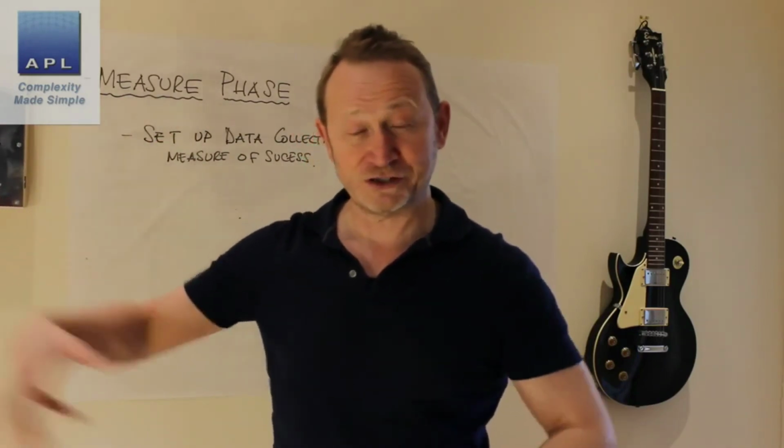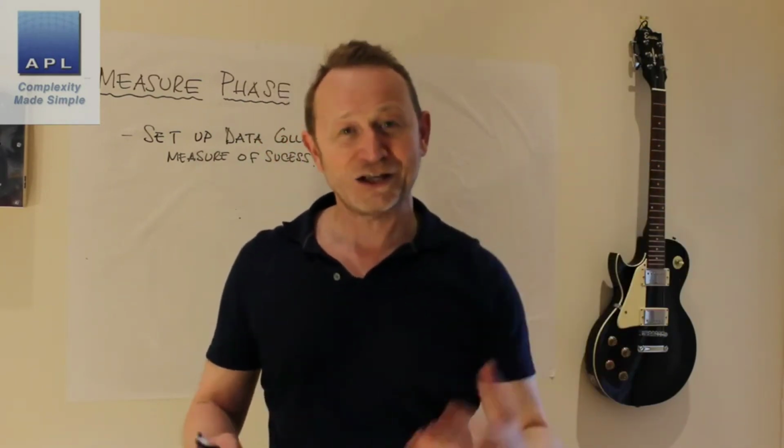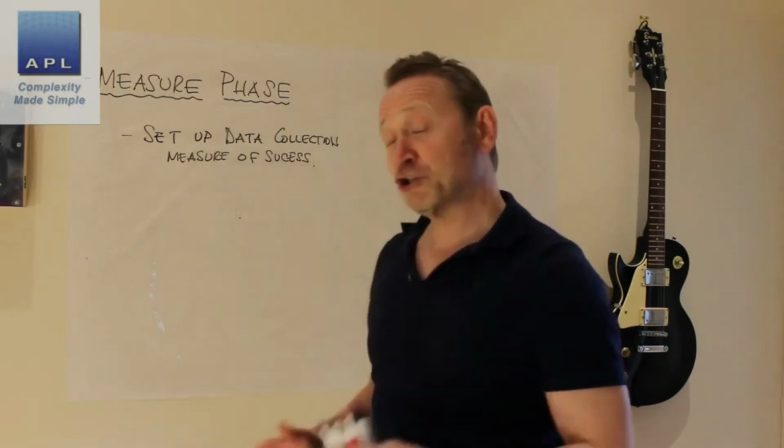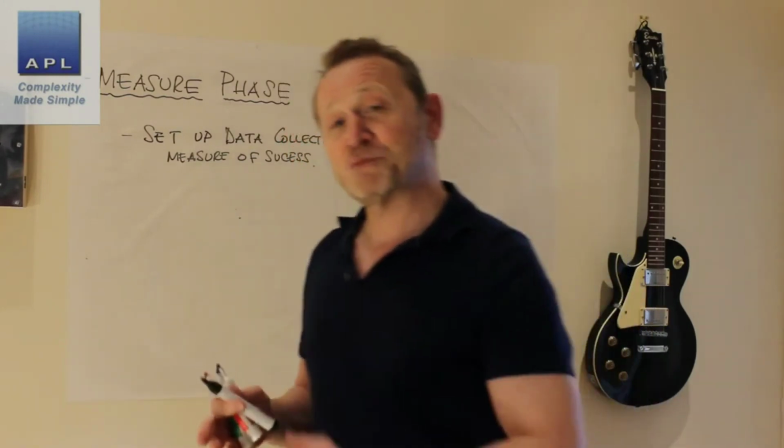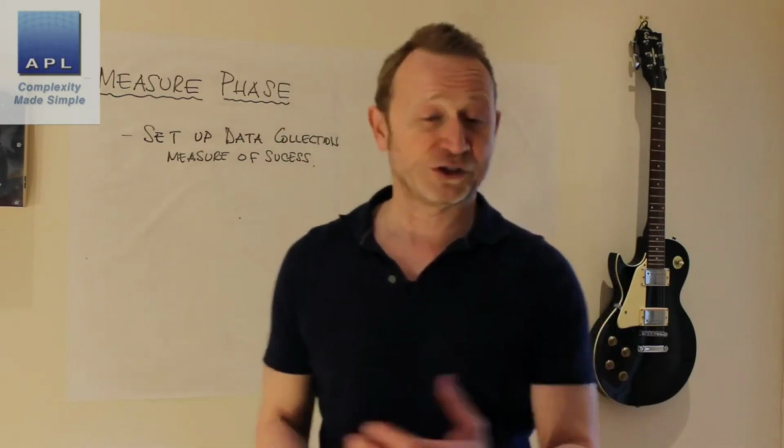So it could be end of line test. So you might do an end of line test. Problem has been picked up and it's been decided that the problem was way up the process, and currently we don't measure for whatever it is that's causing the problem. Could be that the customers picked it up. You know, by the way, the worst place, let your customers inspect your mistakes. It's the worst, most expensive place you can put your inspection process, by the way. But then it could be that you don't currently look for it, so it's something that's come up. It's not something that you look for.